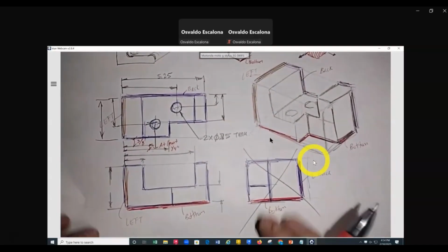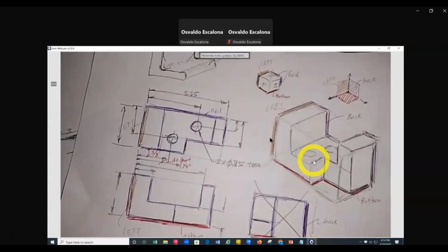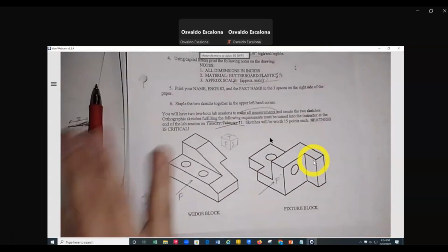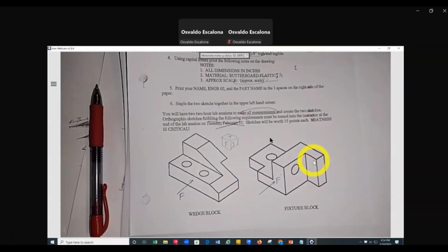I will start here. So let me see, where's your assignment? Let's take a look at it. Do I need the views? Let's test it. This is to be your thinking, right? Do I need the view? So do I need this view to manufacture it? Well, I have an angle, and that angle will most likely be identified by knowing this distance and that distance. So I need that view, I need an angle. So I need a side view. So you have to notice this a little harder. I need the 3 views for this one.